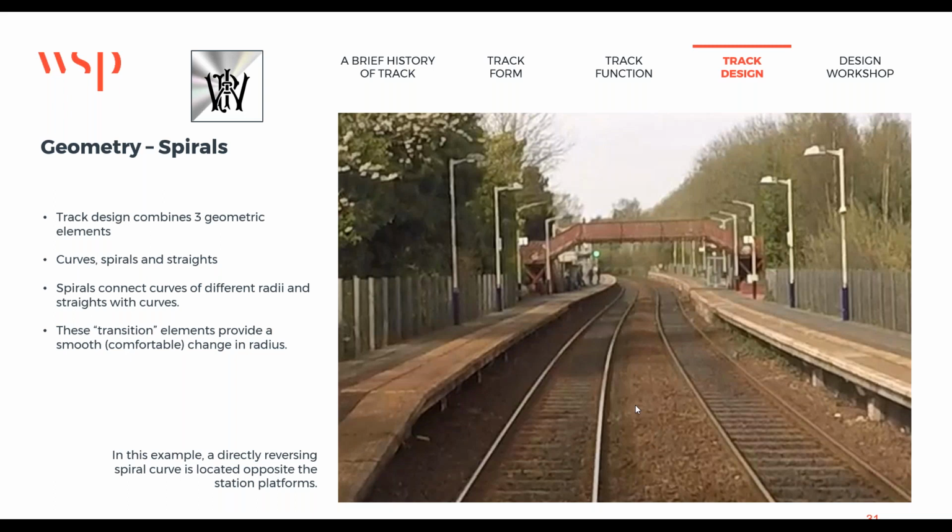Yeah, well, if you think about as the ballast loads, it loads vertically. It's also got some sort of lateral loading at the same time, and obviously the ballast crystals are stuck together, long faces together. But on the HARP units on this side, there's more resilience here because they've got more room to move than they have in here where they're confined. So this track here will be a little bit stiffer than this track here.